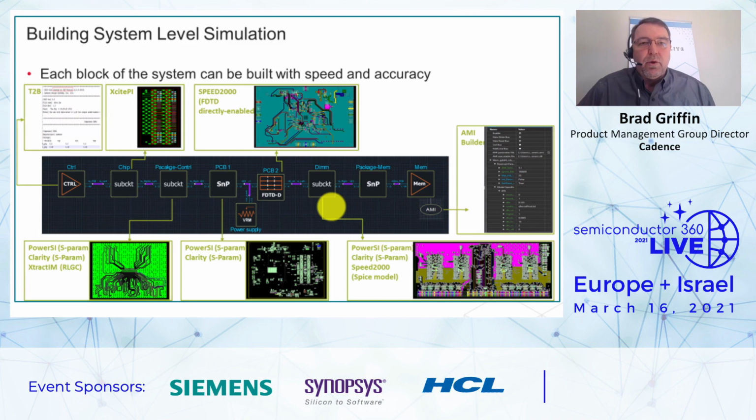And let's be honest, you've got 64 bits of data, you've got 64 bits of address bus, you've got command, you've got strobe, you've got many signals that you're going to have to extract. This is way beyond what many people consider a reasonable thing to consider for a full wave 3D field solver. But we need to take a look at what we can do as a methodology to support that these days.